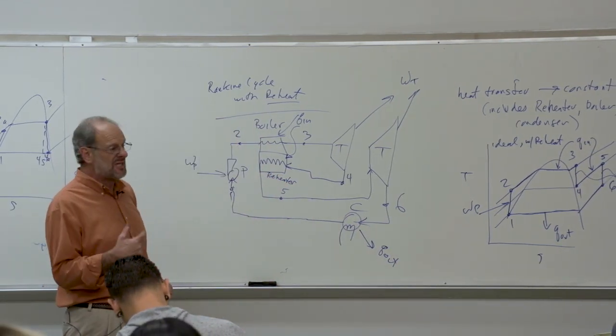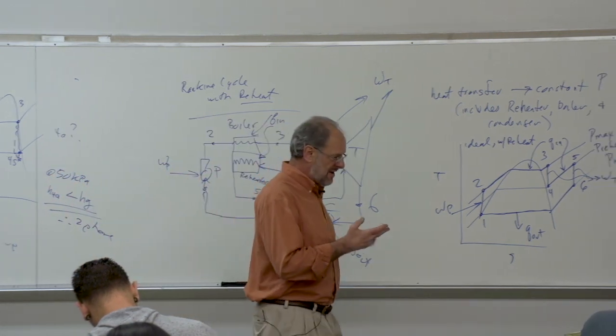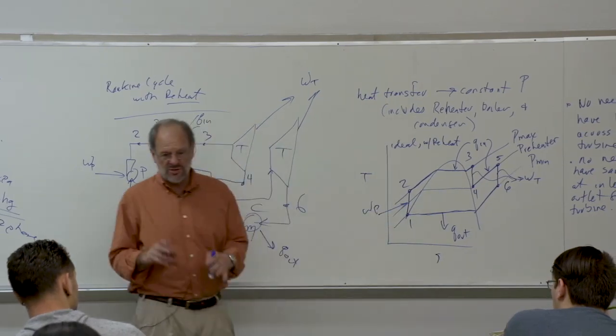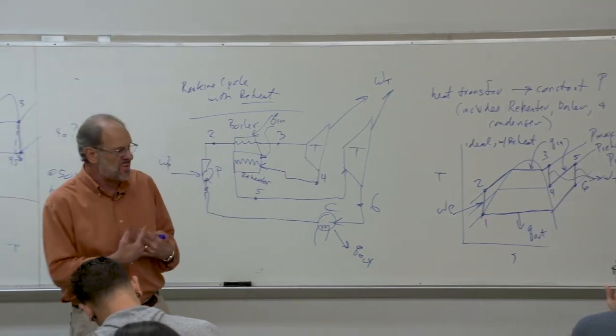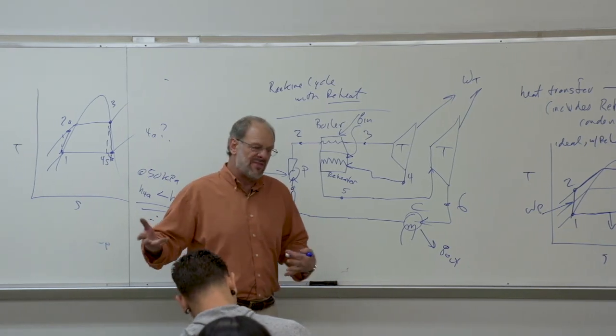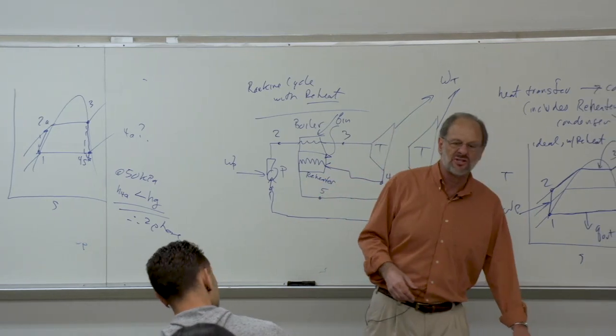In fact, what I've generally seen is you typically have 3 work devices that run in parallel to one another, particularly for the pumps. They're all at 50% capacity, so you can run 2 pumps at 100% while doing maintenance on the 3rd pump, and then cycle that 3rd pump back in and keep running the system without having to shut it down.